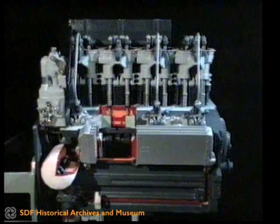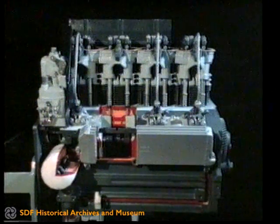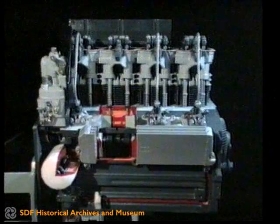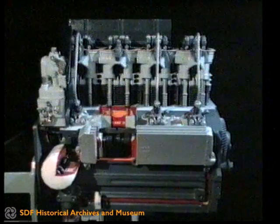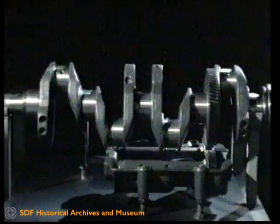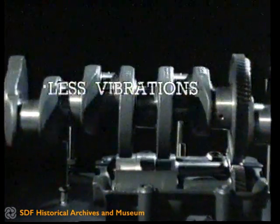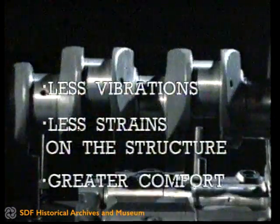In the 4-cylinder engines, the crankshaft and the parts in reciprocating motion generate alternate inertial forces of the second order. In order to compensate for such forces, the 4-cylinder engines are provided with 2 counter-rotating weights, which rotate at twice the engine speed, that is, at the speed of the alternate forces of the second order. Less vibrations, less strains on the structure, greater comfort.